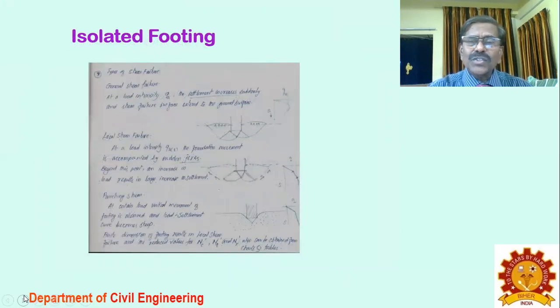If you take the isolated footing, there could be a possibility of failure because of local phenomena happening in the soil. For example, the general shear failure, which is because of the movement of the failure shear zone in the soil, is accommodated by the Terzaghi bearing capacity equation. If it is a local shear failure, maybe if the settlement is very sudden or unequal, then you need modifications in the constants.